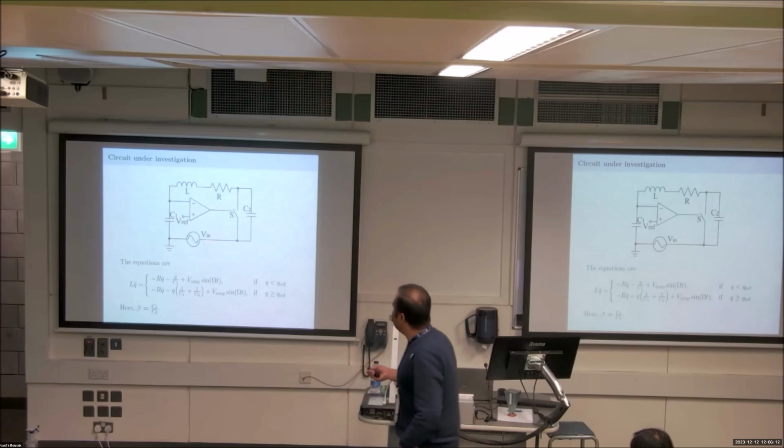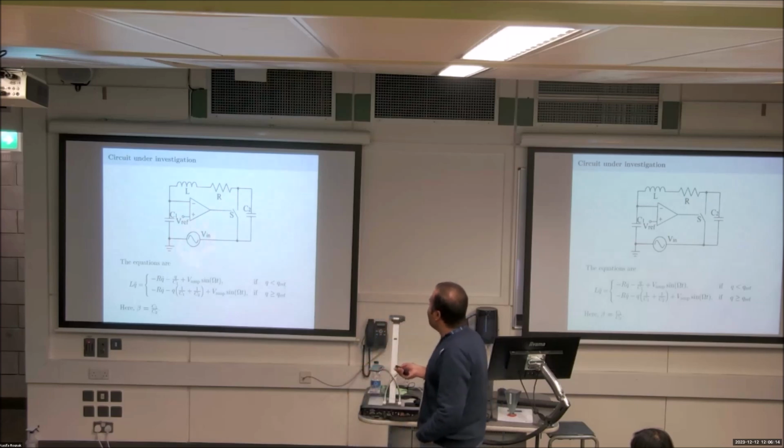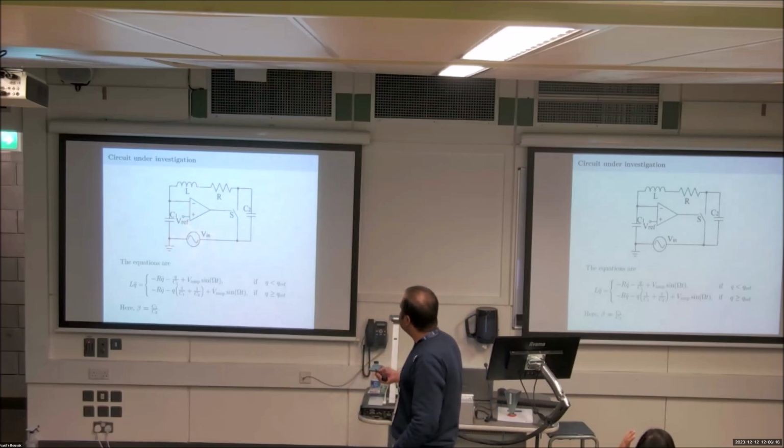In an electronics lab, you will get this function generator easily, and this will be a sinusoidal voltage. And when the voltage across the capacitor is higher than Vref, then the switch will be off, and the parallel capacitive branch will come into existence. And this system will exactly mimic this equation. And here the stiffness ratio is nothing but the ratio between these capacitor values. When C2 is less, beta will be high. When C2 is high, beta will be low.